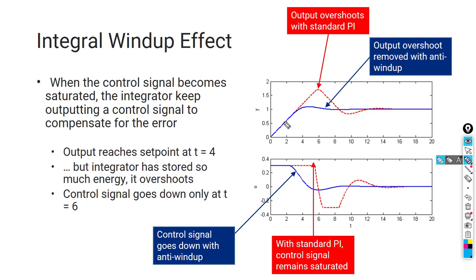Do we add a filter to prevent the signal above 1000 RPM? We'll see in the next slide what we do to implement the anti-windup effect. But for now, just understand the difference. That's the windup effect that you can see, when the signal saturates and I'm having saturation.